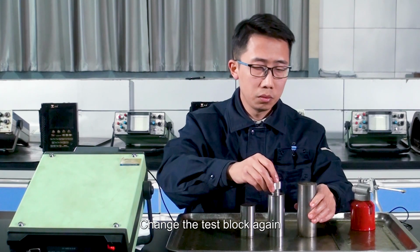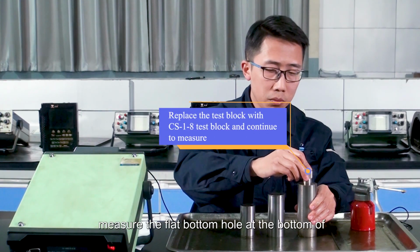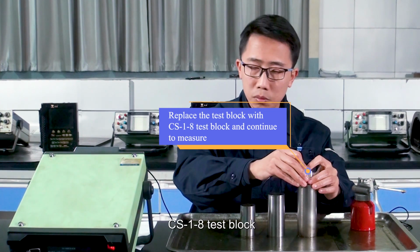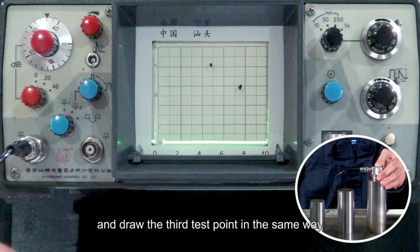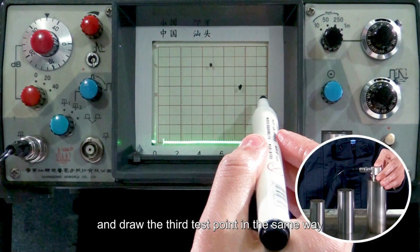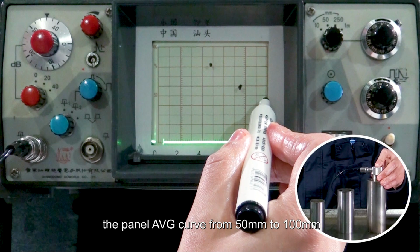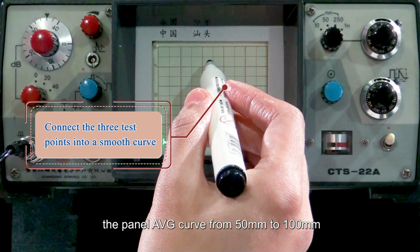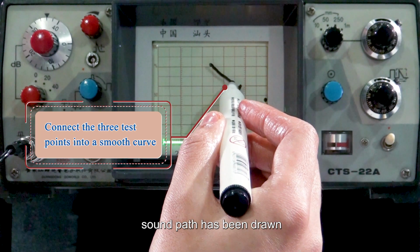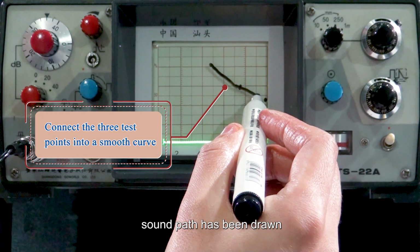Change the test block again, measure the flat bottom hole at the bottom of the CS-1-8 test block, and draw the third test point in the same way. So far, the panel AVG curve from the 50 mm to 100 mm sound path has been drawn.